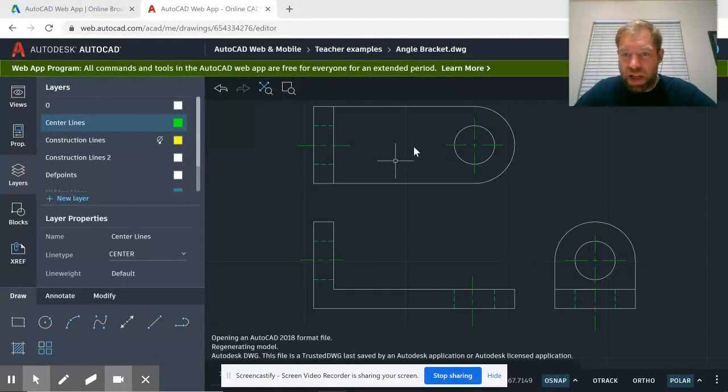And you can see those take place in these circles here, and they signify a circle. If it was a square, it wouldn't need a center line, but because it's a circle, you can put a center line, a center mark, in them. And it's just a crosshair.